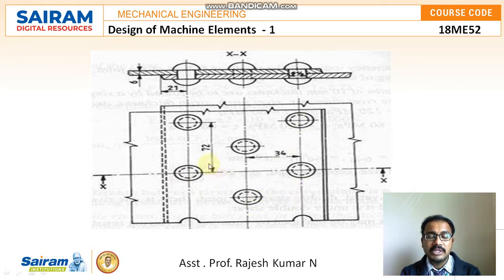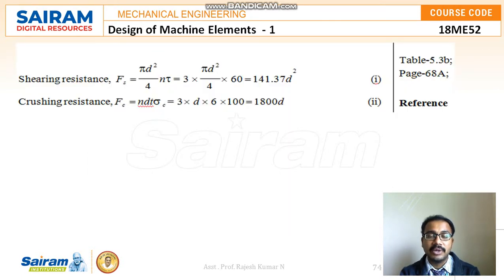Triple riveted means there should be 3 rows of rivets, and these values I have put in directly, but after the calculation I will tell you how I got them. It is a single shear because there are no cover plates and no gaskets. So single shear will be there in both the plates, and we have to find out the pitch, transverse pitch, margin value, and even the diameter of the rivet hole and rivet. All these things we have to find out.